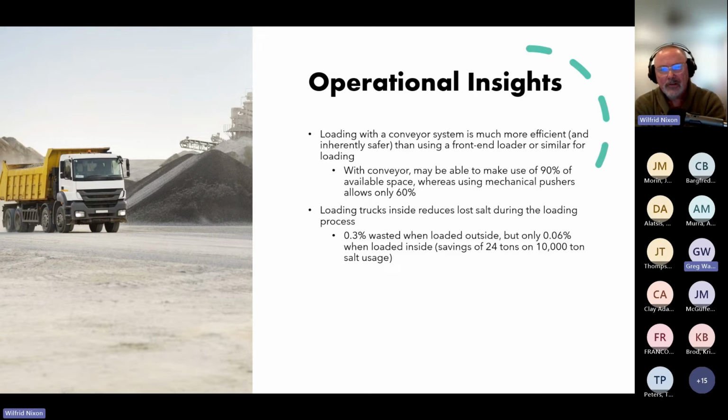And the literature suggests that with a conveyor, you might be able to make use of as much as 90% of the available volume inside the structure, whereas mechanical pushers of one sort or another allow only about 60%. So if you are constrained on size and you want to maximize the volume of salt you can store in that size, a conveyor system is definitely worth considering.